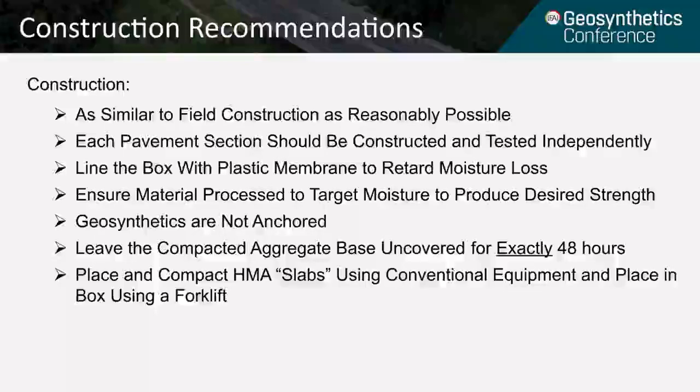The compacted aggregate base should be left uncovered for exactly 48 hours after compaction. It is extremely important that each model pavement section be treated exactly the same and that the test cycling not begin until the exact curing period has been exceeded.